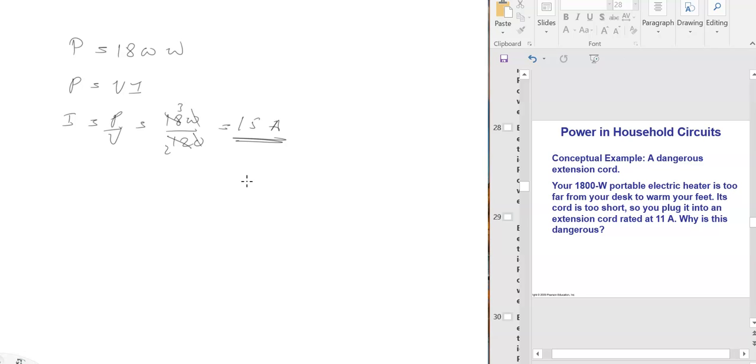Things like not touching electricity with wet hands. Wear insulated shoes when dealing with electricity, like rubber slippers or rubber shoes that are dry. They shouldn't be wet. Don't touch wires directly if they're exposed, and if you're not sure about it, don't touch them directly. Electrical repairs, if you are not trained to do that, don't do it. Get a trained person to do that.